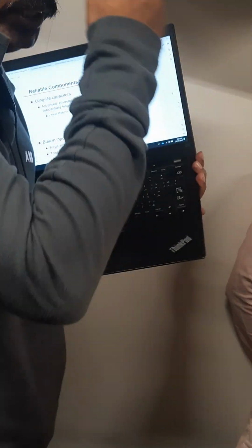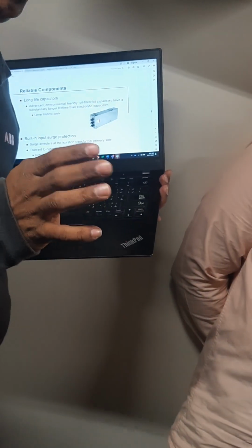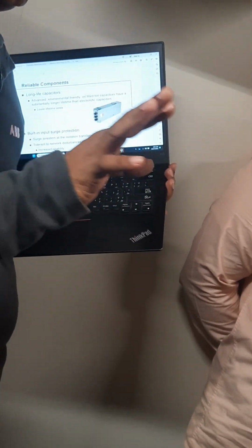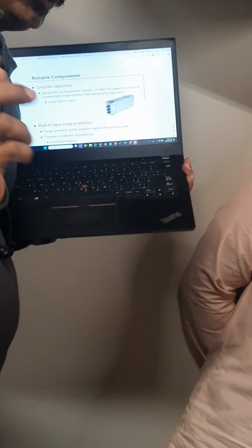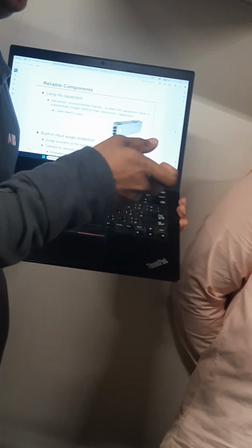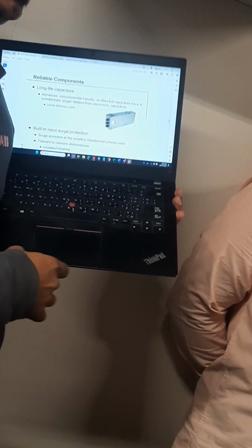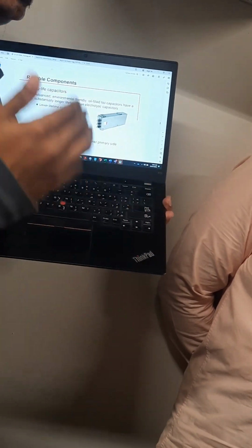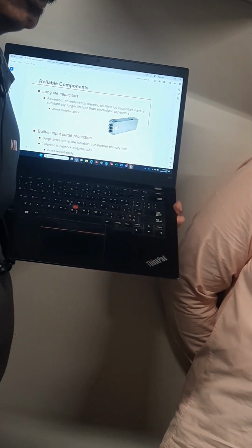Whenever you do a PM activity, like replacing the filter or something, you need to switch off the drive for safety reasons. You will not be able to open the door until you switch off; otherwise it is interlocked. If the door is not properly closed, you cannot operate the isolator switch either. Whenever you have an issue, you can call ABB and we will help you.